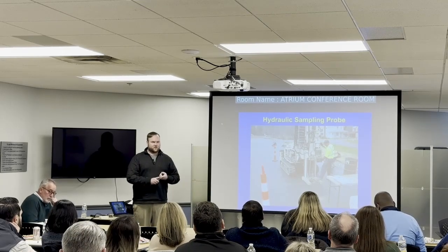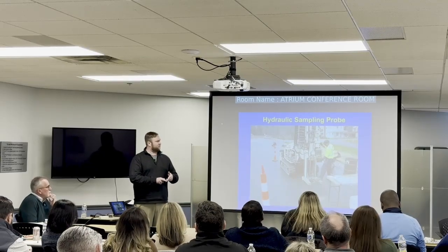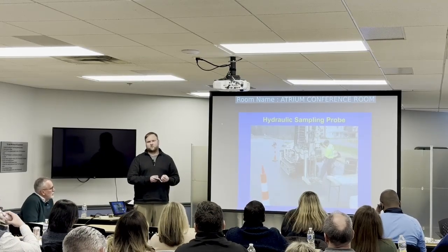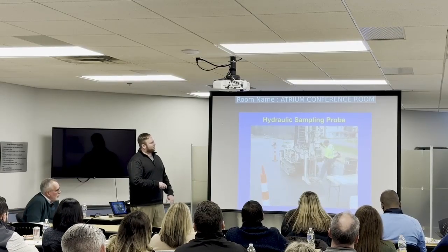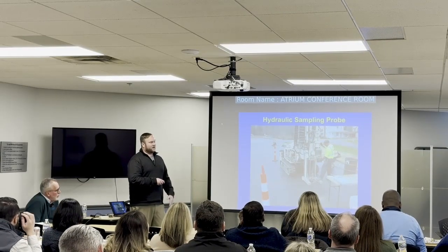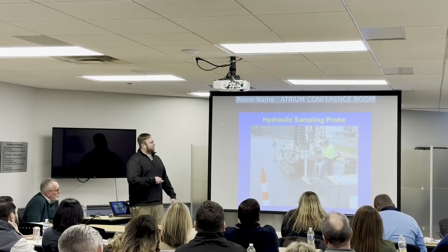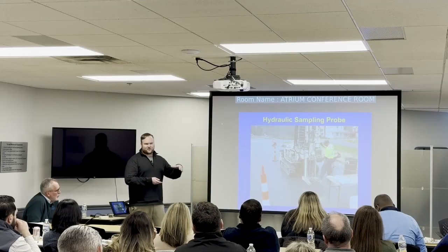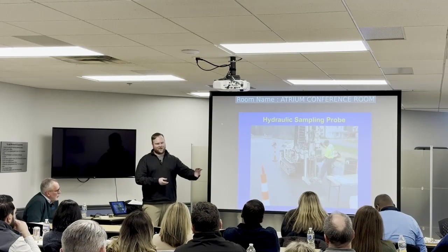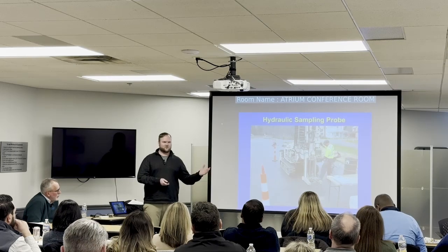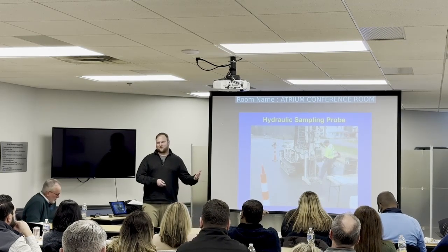So there's no drum management. You don't have to worry about additional costs for analyzing that soil to see if it needs to be treated as hazardous material and trucked off site. When we do work at cluster facilities, sometimes we will generate these drums. They have to be tracked, they have to be managed properly, so it's additional cost. But just so you're aware, sometimes if you walk behind a Speedway, you're probably going to see a drum with a non-haz sticker on it that's been there for 20 years, and it's because somebody forgot to track that, and it's going to show up in the phase one site visits that we do.